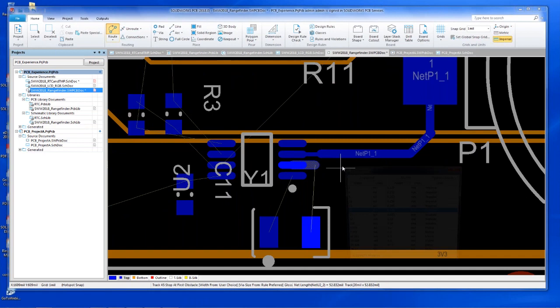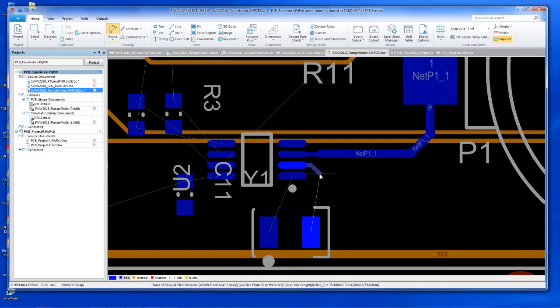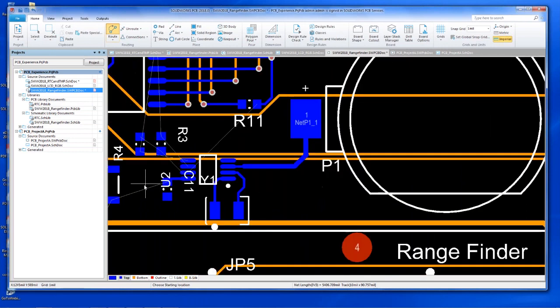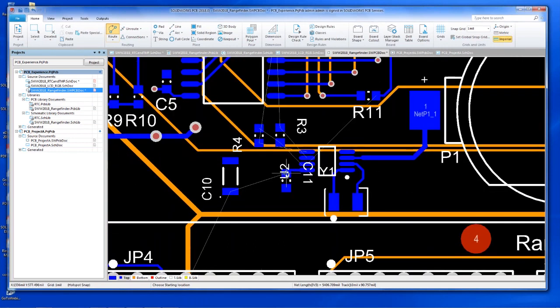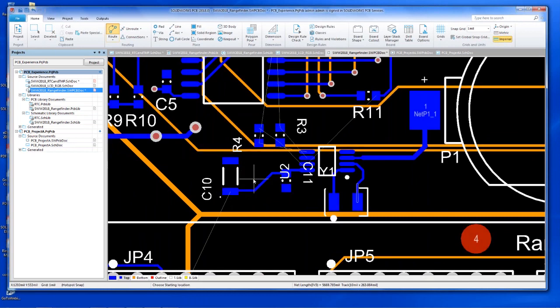Now our trace width remained at 20 because we set it to 20. So we'll drop it back to 10. And we'll just route up this guy. And again, control left key finishes that. We can bring this off, finish that, route some power traces, and again, quickly and easily connect up our circuit so that we can finish the design for manufacturing and prepare to go to SolidWorks.